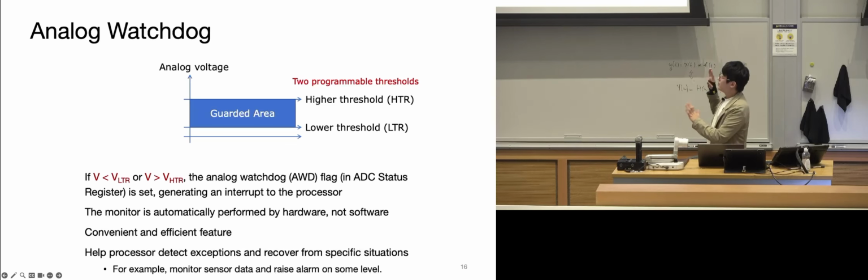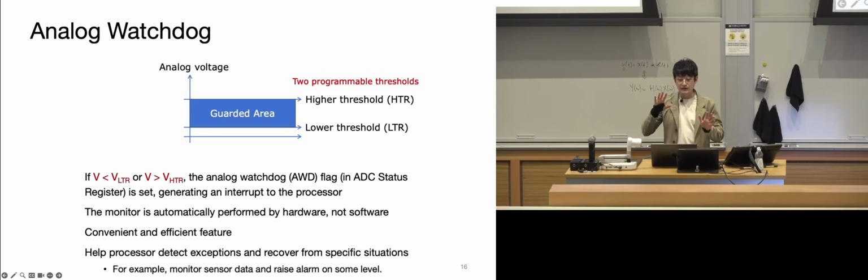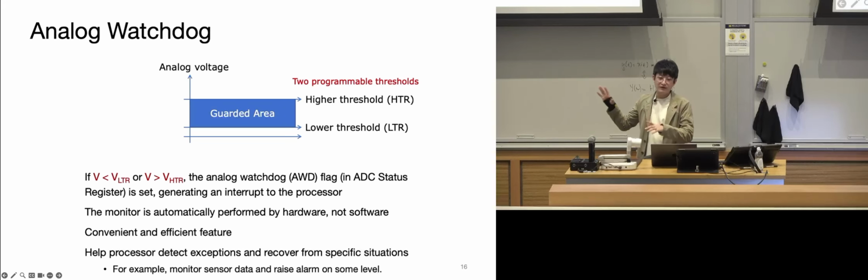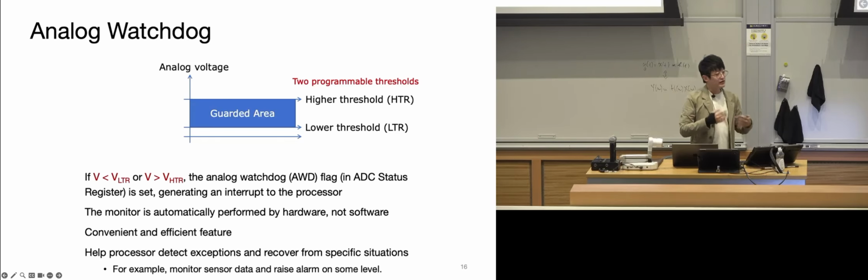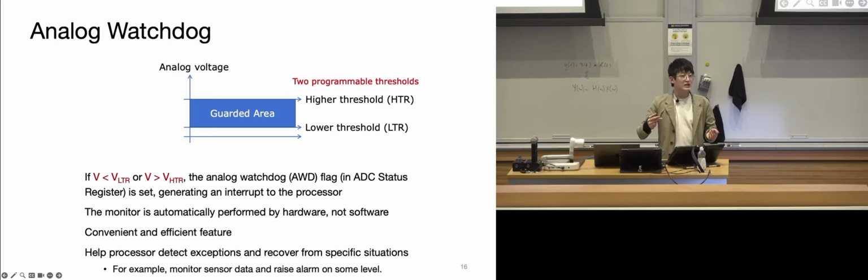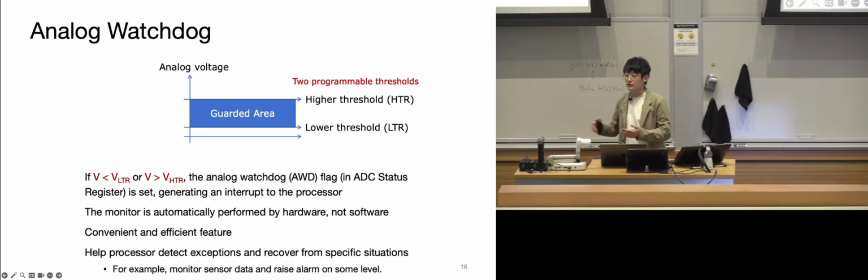And this can be done at the hardware level. You can imagine this being very useful for embedded systems that run for a long time, but you don't have to have it working all the time. So you just put it in sleep mode most of the time, and whenever there is a trigger signal coming from the ADC channel, that becomes a wake-up for the entire system to do something.